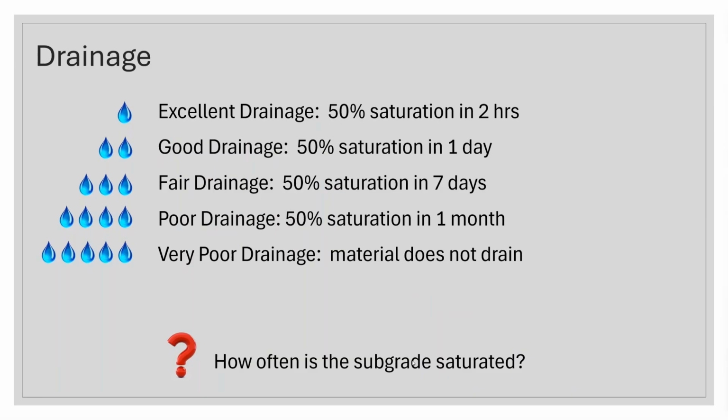So remember, we're talking about what's down underneath. After everything's been saturated, how quickly does that get removed? And there are some places where it really does not ever get removed. So the other question is, how often does your subgrade get saturated? The more often that happens, the more damage you're going to see.